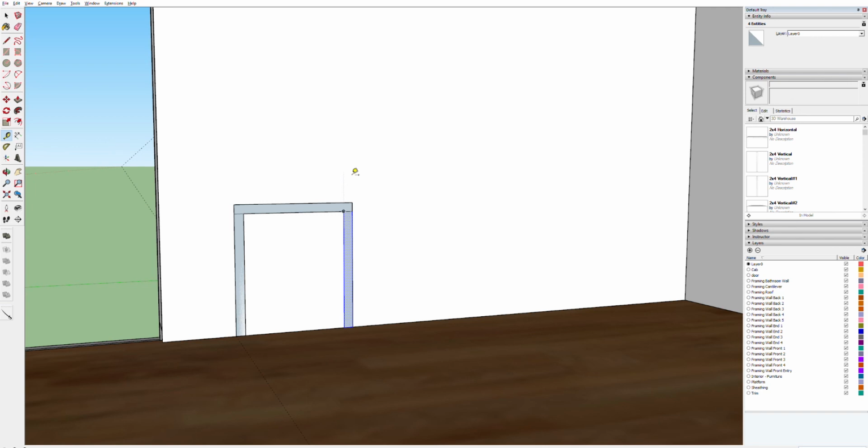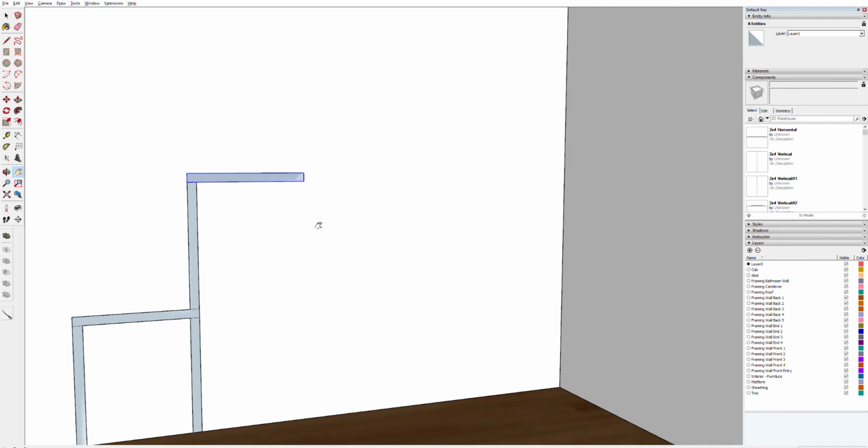Okay, so now that we're on our second riser, the rest of the risers are all 10 and 13/16, so I'm going to draw that using the rectangle tool. Okay, and we can use the same tread that we just had. Now I'm just going to draw this pattern up the rest of the way. I'm going to copy these in pairs, like so.